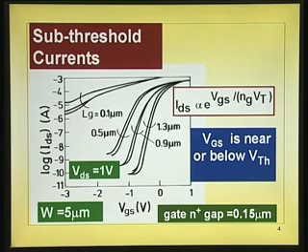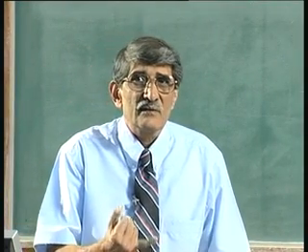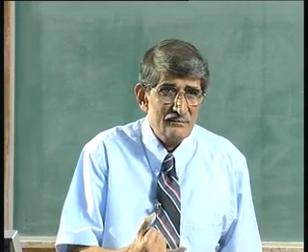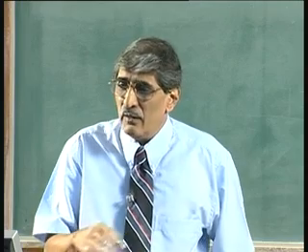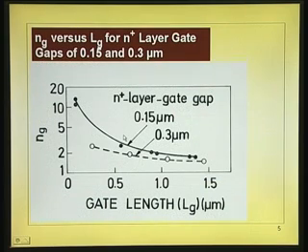You go to shorter and shorter channel devices, one thing that happens is your threshold voltage changes. You may say, okay, I do not mind that much, but you will have to mind when you talk of integrated circuits. The other thing is you are not able to turn off your device so easily. You must apply much more voltage to turn it off compared to this device. So, in shorter channel devices you get the two dimensional effect.